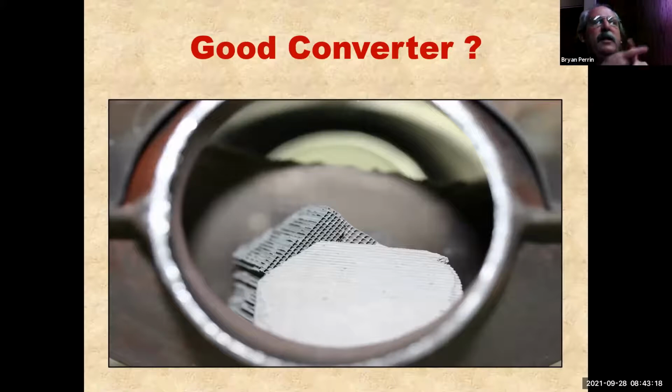So if you replace a catalytic converter and do not break it in, and they see this a lot back east in the wintertime, because they'll put a converter on, they'll go park the car, no one will drive it, get it hot. The customer drives it for a couple months on rough roads. And then when the winter's over, it finally gets hot enough to pop the blanket, but by then the biscuit has already been vibrating, it's undersized. So now it continues to vibrate and come apart. That is one of the big issues they have with converters. That's probably the number one biggest warranty issue with replacement converters. So you do actually have to break them in for them to work correctly and last.